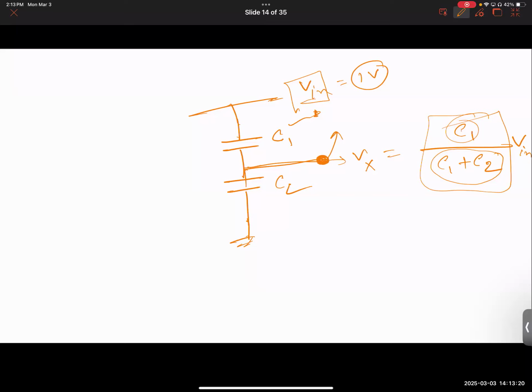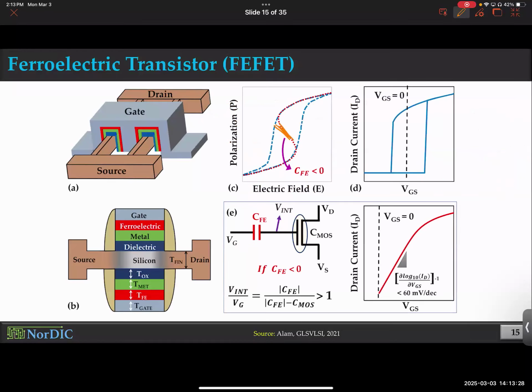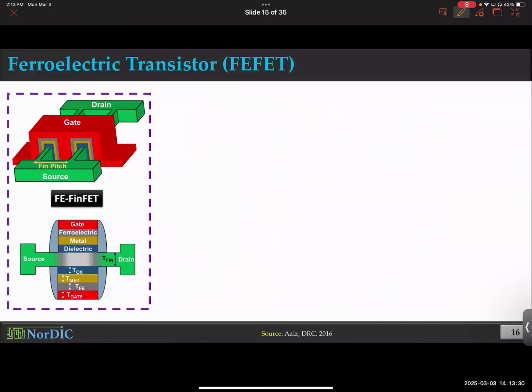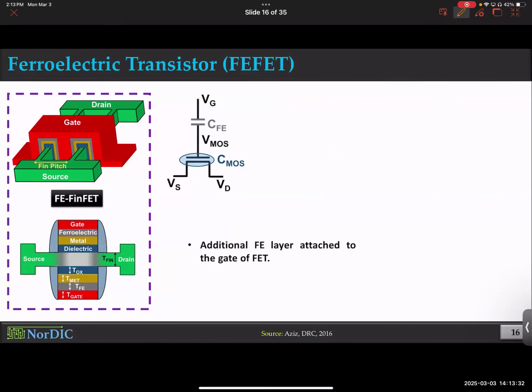So far? Okay. And the stack that I've just drawn, I hope the 335 folks can remember, is basically the gate stack of a MOSFET. Notice this: forget the ferroelectric. You have the gate, which is the metal, then you have the dielectric, and then you have capacitance coming out of the semiconductor. So you have two capacitors back to back in the gate stack of a MOSFET.